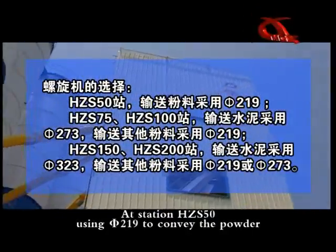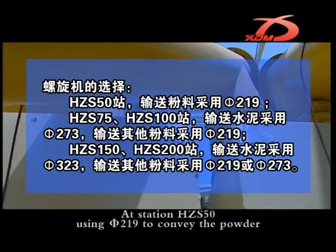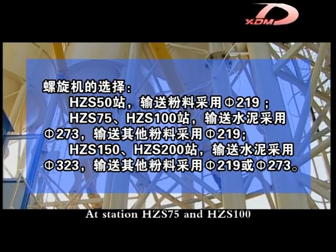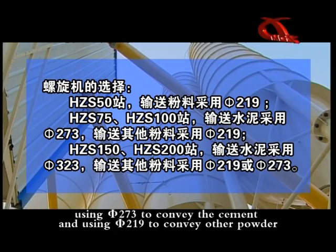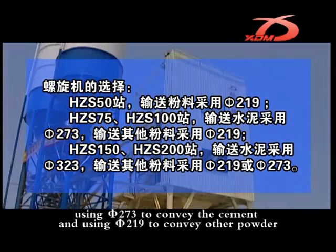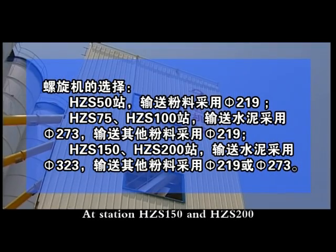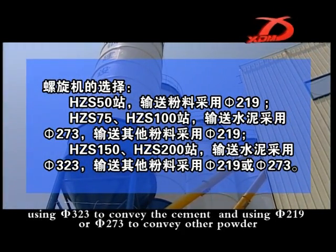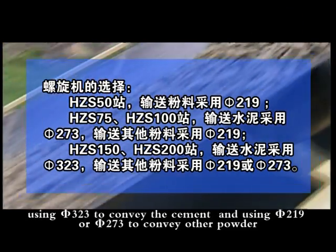Selection of the screw conveyor. At station HZS50, using diameter 219 to convey the powder. At station HZS75 and HZS100, using diameter 273 to convey the cement and using diameter 219 to convey other powder. At station HZS150 and HZS200, using diameter 323 to convey the cement, and using diameters 219 or 273 to convey other powder.